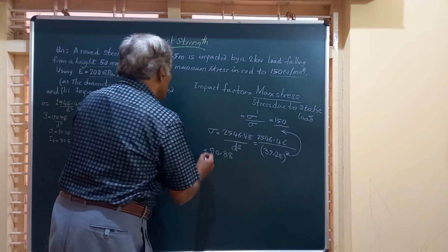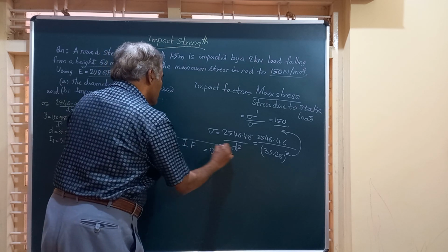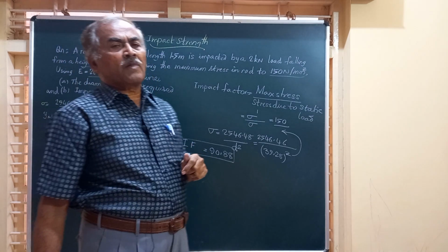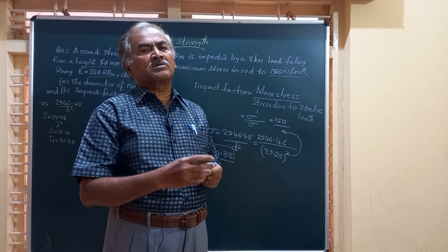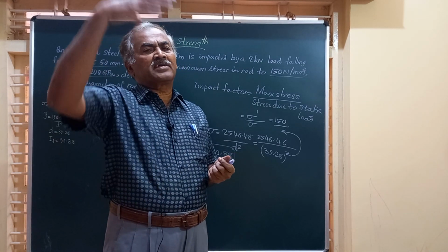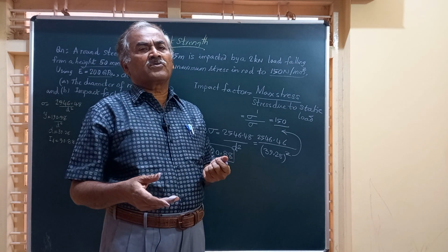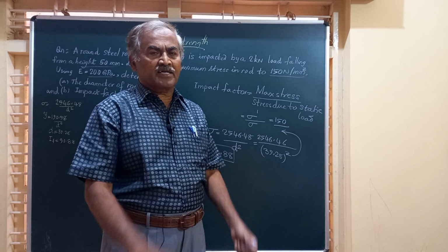It's a number, so I will say impact factor IF is equal to 90.88. Friends, this impact factor depends on parameters like the weight that is being dropped, the height of drop, and the material properties such as Young's modulus, etc.